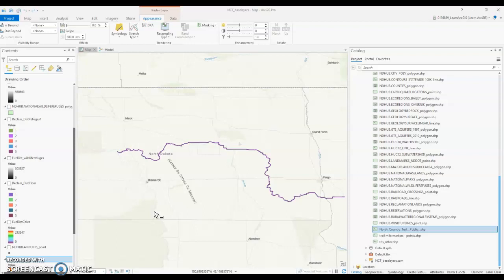This time we're going to be going over how to use the Euclidean distance tool, what it's used for, and then also using the Reclassify tool to put unique values to our data. First, it's going to be set up the same way that we did the buffer tool, essentially the same process. We're going to have to use the model builder, and we're going to have to search for tools, etc.